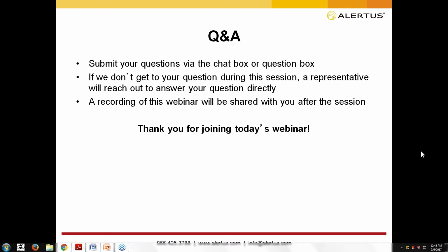Other customers want to activate when there's an alarm, when there's a supervisory condition and a trouble. Obviously, those activations would be different. And then some other people also want to activate when there's a reset, which would mean hopefully an all clear would be sent out as well.